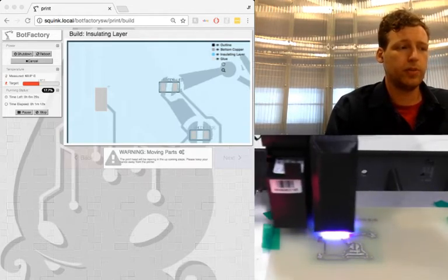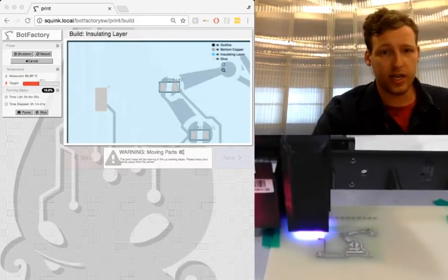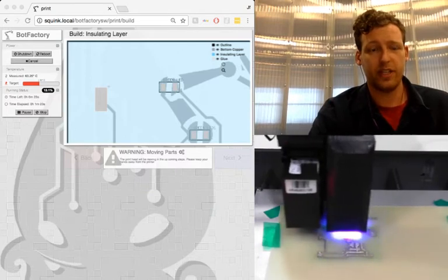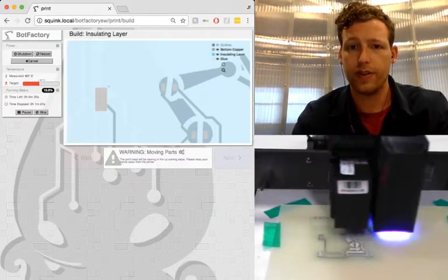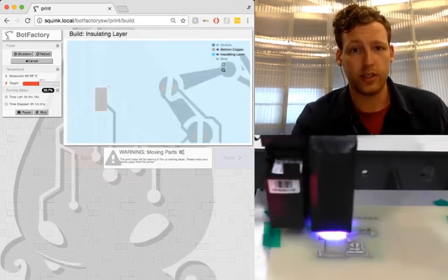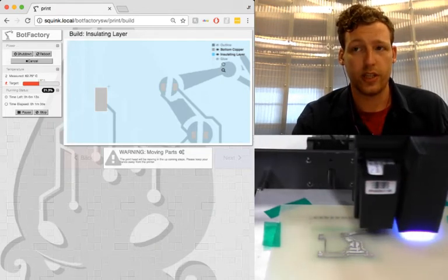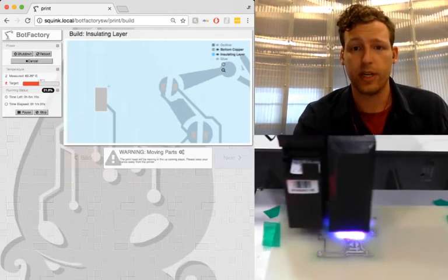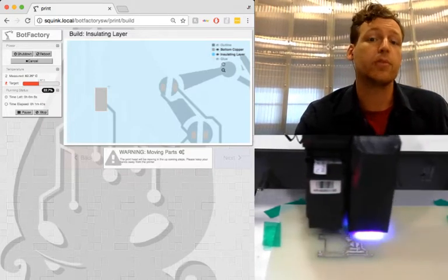But you should be fine with 2 in this case. And it's going to be printing everything but where the pads need to be exposed. So, going back here, let's turn off everything. This is what it's printing, and this is what exists underneath. So there's going to be areas open for the connections of the LEDs and the battery here. If this is a two-layer board, these would be the vias, more or less.